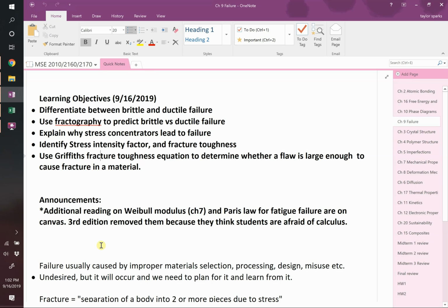Okay, this time we're going to compare what Garrett did, which is a slow deformation, but we're going to do a difference. This time we have our ceramic knife, because we're not barbarians. Remember? Yttria stabilized zirconia, transformation toughened. Notice the tip is broken. They're still relatively brittle. My kid still broke this and broke the tip off of it, right? By dropping it. So this time we're going to do the same thing in terms of slow deformation, but I'm going to introduce a pre-crack, right? I cut maybe a quarter of the way through it, okay? So Isaac, slow as you will. You get really slow if you want. Go ahead and deform that.